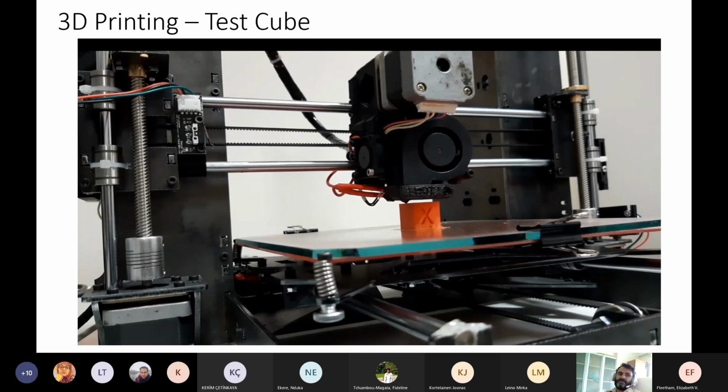In this particular case, our table bottom plate is glass material. As the extruder goes from one end of this table to the other, the distance between the table and the extruder must be maintained. This can be one of the most time-consuming but important calibrations in 3D printing.